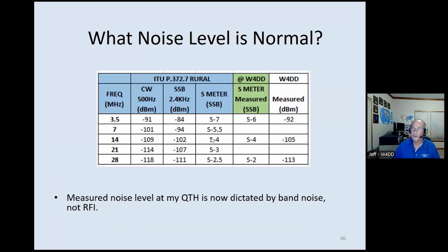So what noise level is normal? Generally speaking, when I do RFI assists, on 80 meters about an S6 is where you expect things to be, on 20 meters about an S4, and on 10 meters about an S2, in rough ballpark numbers. It could be a little better or a little worse, but that's what I think of when I look at issues.